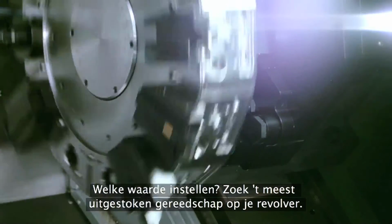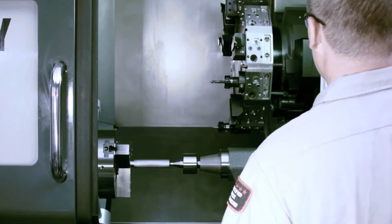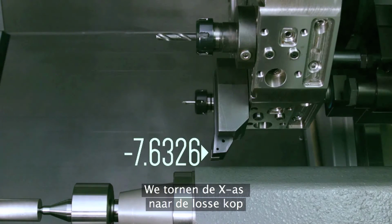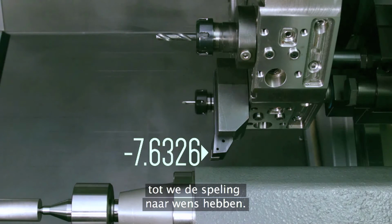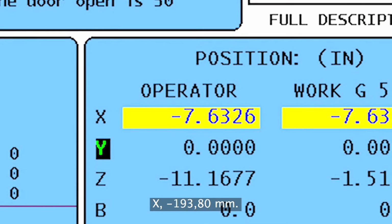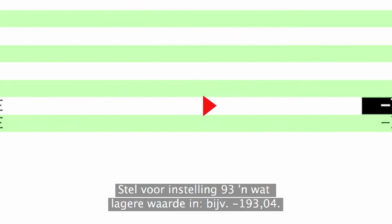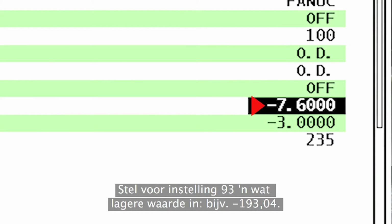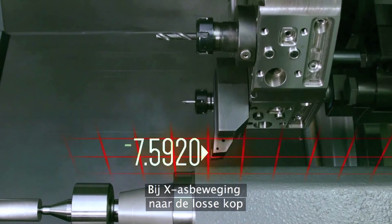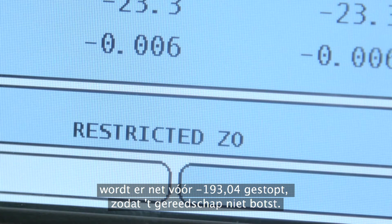So to set this value, find the most extended tool on your turret and use that to check your clearance. So we jog the x-axis down towards the tailstock until we find the clearance we're happy with. Looking at the x-axis position on the screen, the reading is X -7.63. So we'll change setting 93 to a slightly smaller value, like -7.6. Simple. Now, when x-axis motion moves toward the tailstock, it will halt just shy of -7.6 before the tool can crash.